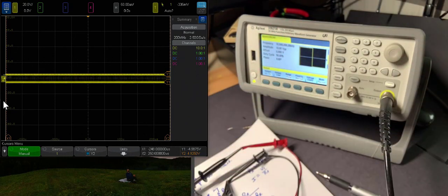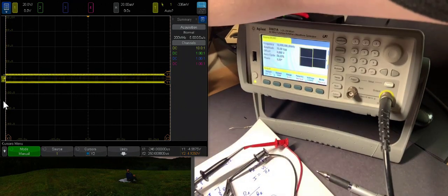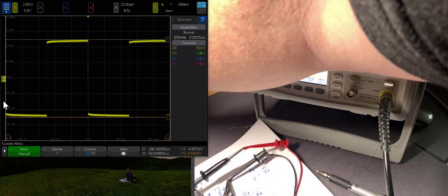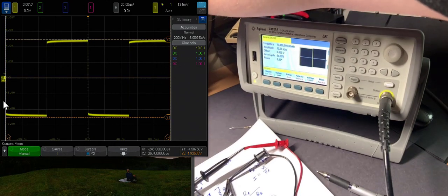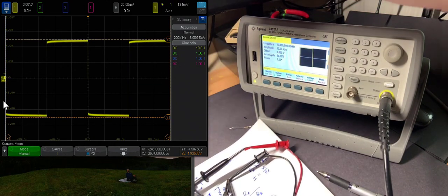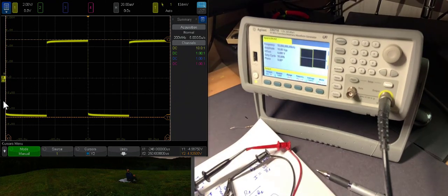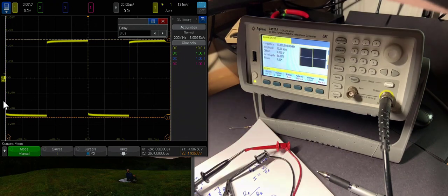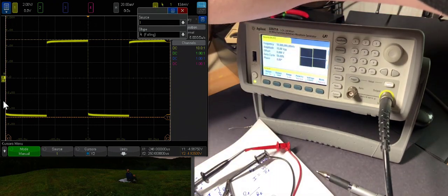And now let's look at our scope and see if we can't see what that signal is. So I'm going to increase the scale, and there we go. And we're triggering in the middle here. And you know what? This is pretty darn close to what we had before. It's not exact, and you'll notice, here is the 0. We've got it set for falling edge. Let's look at the rising edge initially.